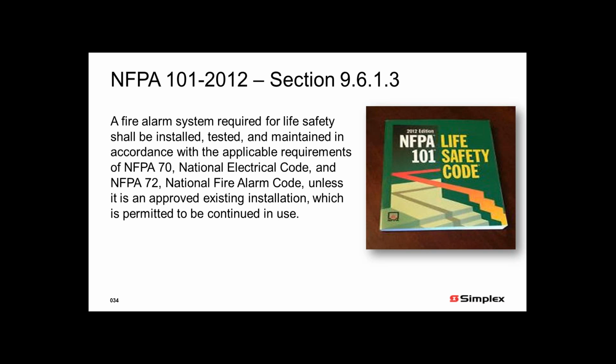So our building codes, like NFPA 101 or the I codes, are going to say, in this occupancy, you shall put in a fire alarm system, but you're going to install it per NFPA 72, or a sprinkler system per NFPA 13, and so forth. So a code tells us when to do it, a standard tells us how to do it.